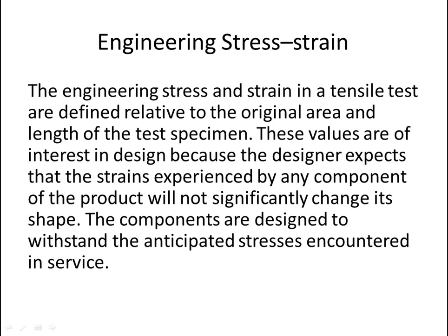Let's talk about engineering stress and strain. The engineering stress and strain in a tensile test are defined relative to the original area and length of the test specimen. These values are of interest in design because the designer expects that the strains experienced by any component of the product will not significantly change its shape. The components are designed to withstand the anticipated stress encountered in service.